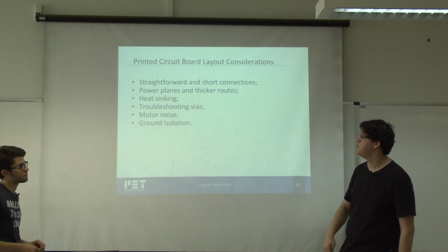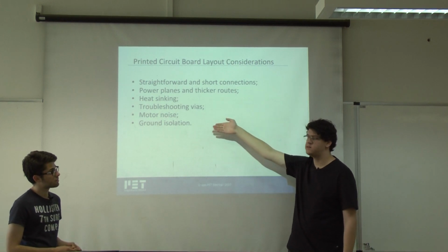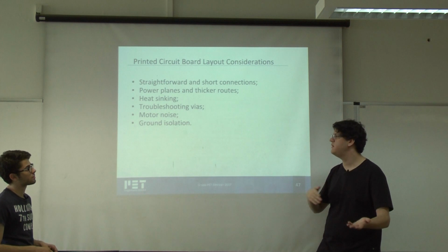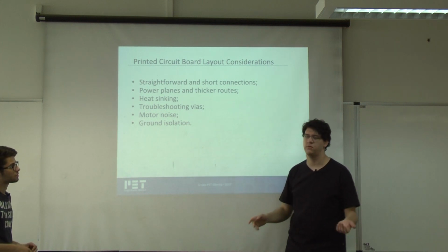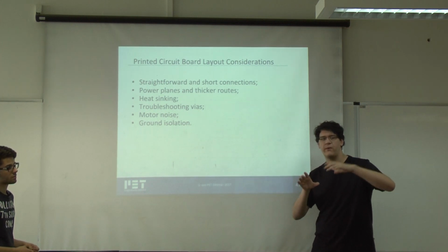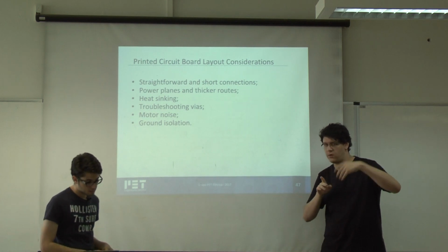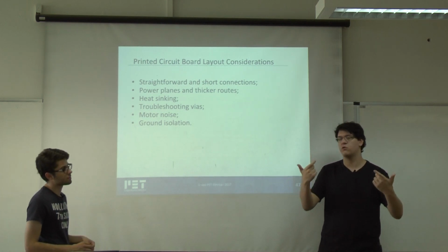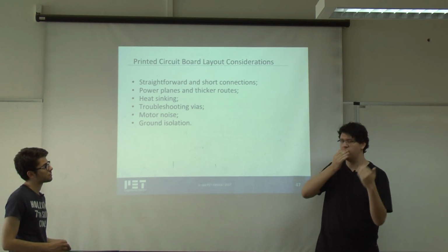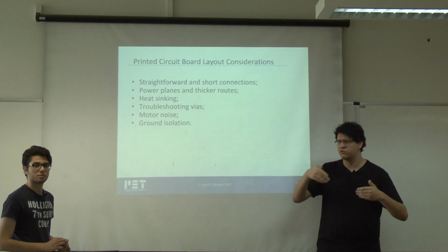And as you said, there is a problem with motor noise, and to deal with it, we use ground isolation. So we isolate the power plane, the power ground, and the control ground, so that the noise from the motor won't go to the microcontroller ground.